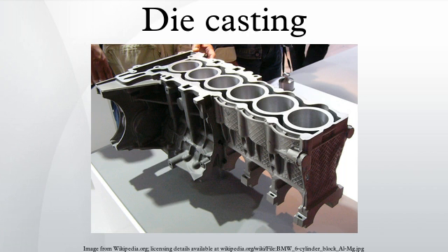Therefore, hot chamber machines are primarily used with zinc, tin, and lead-based alloys. Cold chamber die casting. These are used when the casting alloy cannot be used in hot chamber machines. These include aluminium, zinc alloys with a large composition of aluminium, magnesium and copper. The process for these machines starts with melting the metal in a separate furnace.